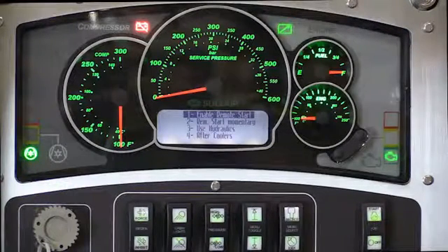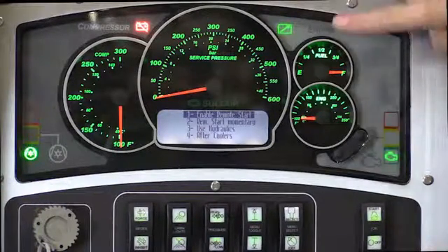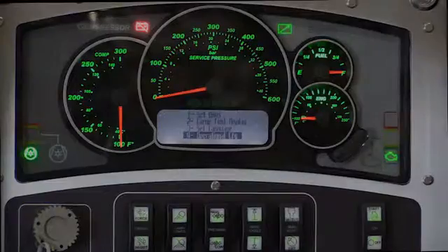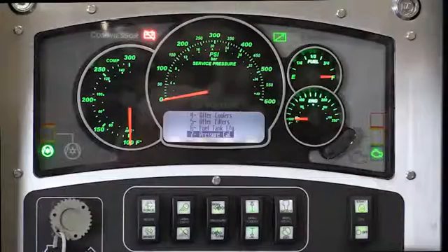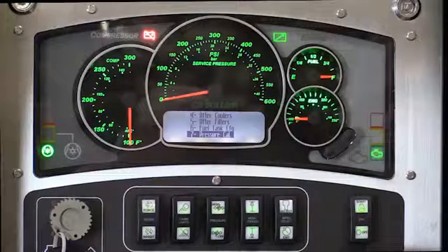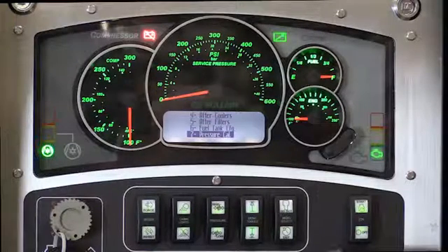Once you confirm your selection, you will be taken back to the previous menu. We're now going to cover the pressure calibration option. This should be done every time you do a check-in procedure getting the unit for the next rental. Once pressure calibration is highlighted, simply use the select button to activate your selection.